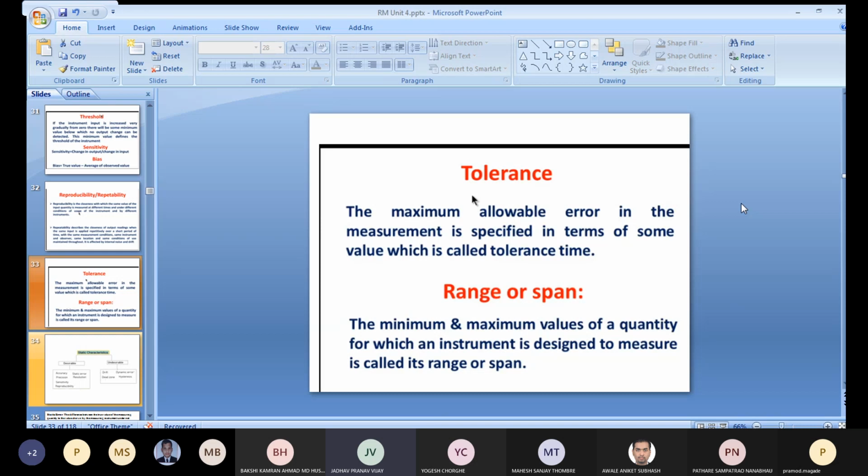Correct. Interchangeability is a term which is very important. Interchangeability means applicable everywhere. It is not like that while manufacturing, suppose, a nut and bolt. Suppose my one component, the nut, is not available. In that case, I will not have to go directly to the market to purchase that single nut. I will go to the inventory shop of my company, and through that I get the nut, and for that particular bolt it is available. So it can fit, suppose M8, M10, whatever it is, as per the standard. That's why tolerances are important.